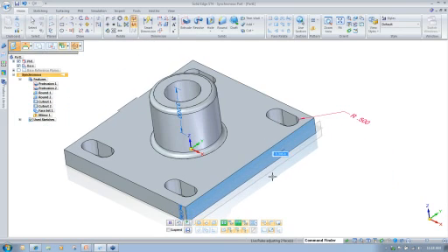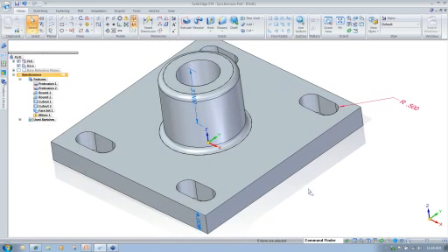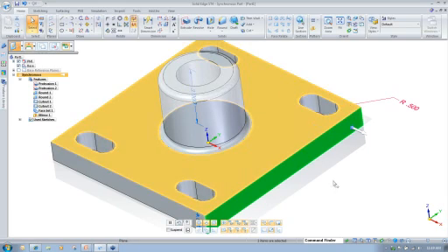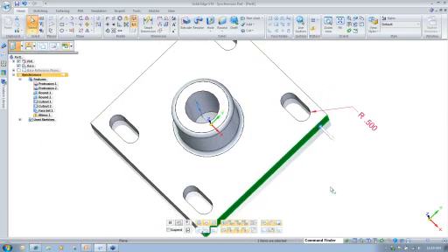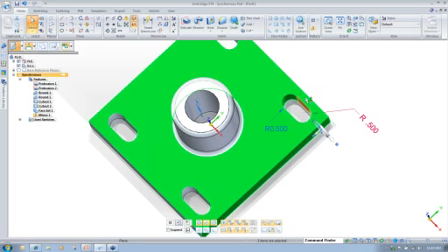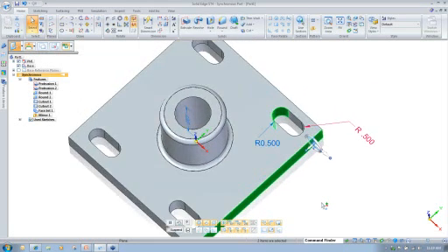Okay, so in this case I'm just gonna bump it out a little bit. So let's say, for instance, that we wanted to move that surface, but we wanted to make sure that those slots moved with it. Now all I'll do is grab that surface, hit my space bar, and again, if you accidentally grab a surface that you don't want, you can simply hit your control key, hold it, and re-click the surface to turn it off.